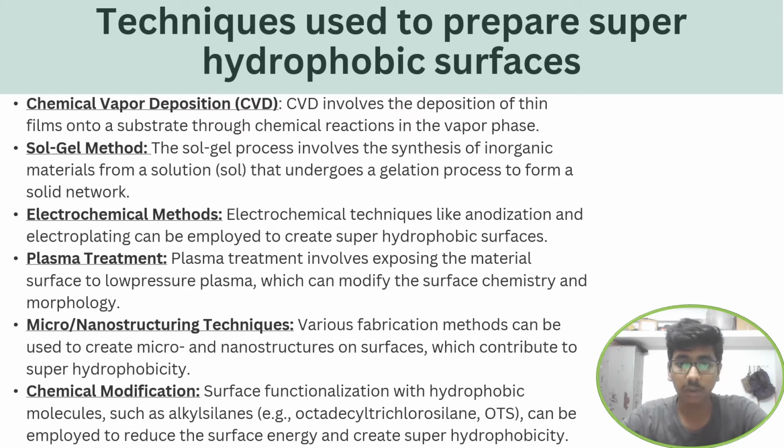Nanostructuring techniques. Various fabrication methods can be used to create micro and nanostructures on a surface, which contribute to the superhydrophobicity. Chemical modification. Surface functionalization with hydrophobic molecules such as alkylsilanes, for example octadecyltrichlorosilane (OTS), can be employed to reduce the surface energy and create superhydrophobicity.